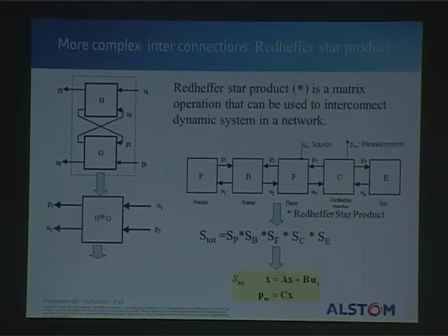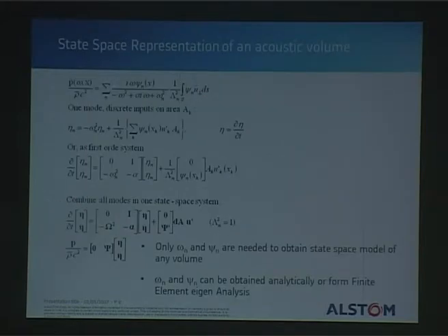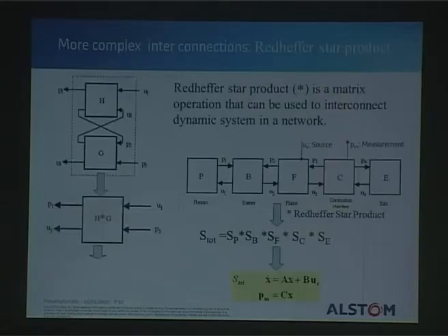But then we have many more parts in a realistic system that we want to combine somehow. For example, we would have a burner, a flame, a combustion chamber, an exit, and a plenum. And remember, these are disconnected with arrows, but we talk about an annular combustion chamber, so you don't have one burner, but maybe 20 or 30 burners and 30 flames, etc. The combustion chambers would be multi-input, multi-output blocks. But we can describe all that with this expansion that I showed on the previous slide. So we get these equations describing, for example, the plenum or the combustion chamber.